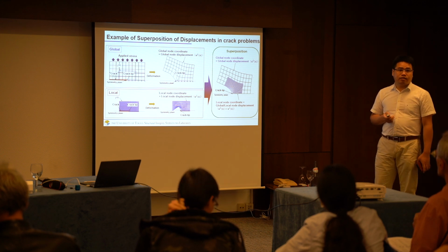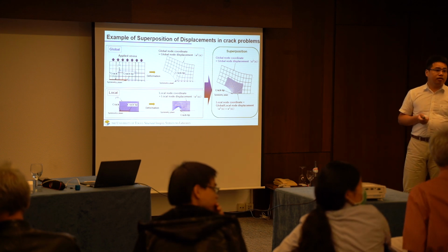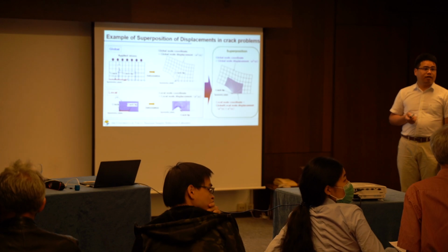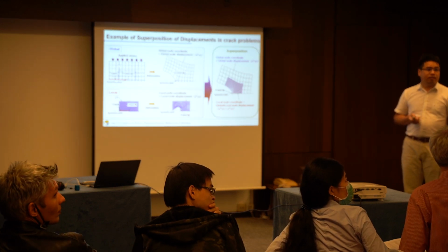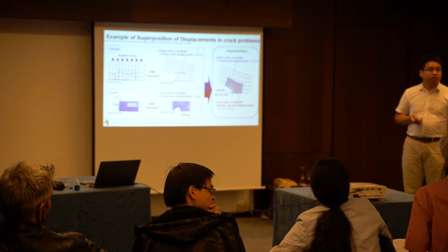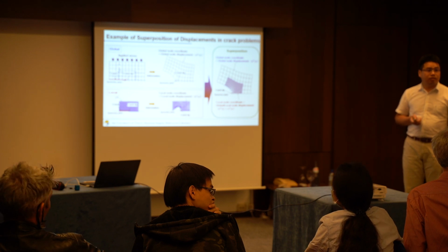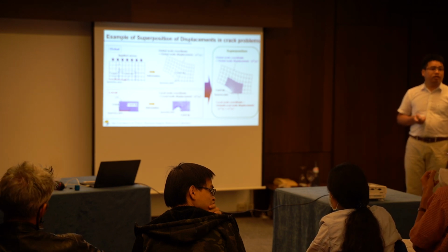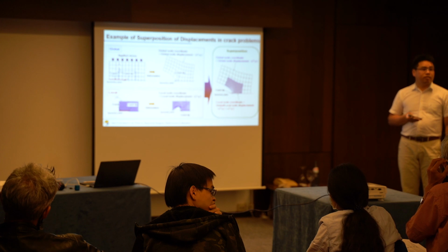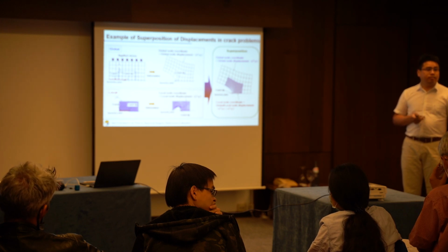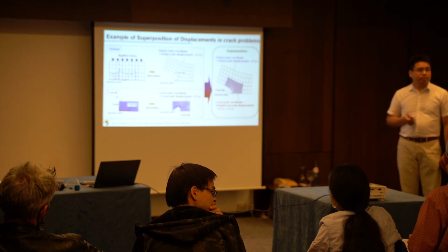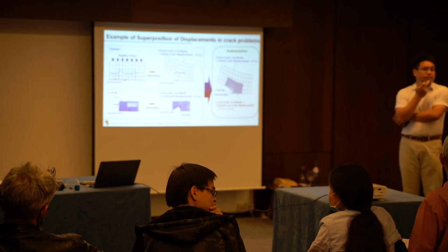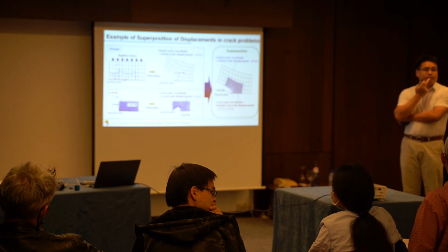Okay, the last question, a quick question. It looks like in Abaqus we have a submodel. So we run the coarse mesh there, and then we do a submodel there. Then this submodel is driven by displacement, as you asked.